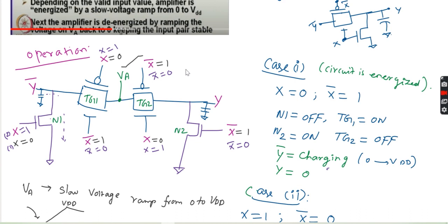We connect the clamp circuit because at the output we have the load capacitance. When I have load capacitance, we need a path to discharge. The very important thing about adiabatic circuits is that in the conventional CMOS circuit, we use a fixed power supply.